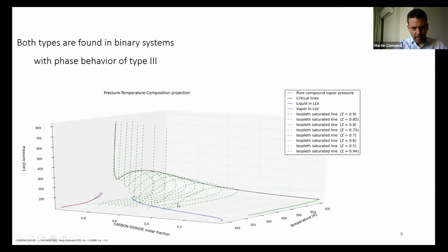So there are different envelopes which are closed here, like the first example before, with the separated liquid-liquid saturation line here. That is for CO2 mole fractions below 0.80, and above 0.80, we have this, you can recognize here, the open envelopes.